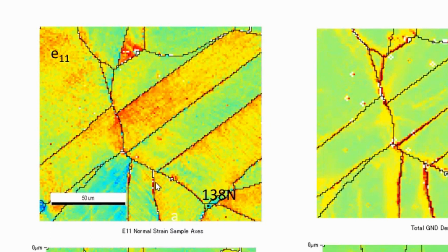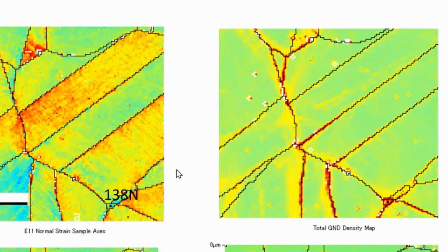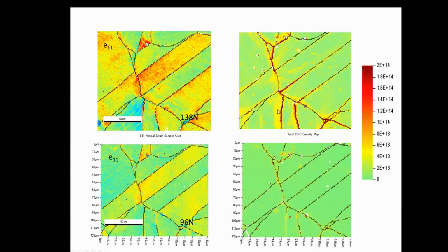And we see little areas where the strain is localized, very, very localized. These are the straight lines I mentioned before, the slip lines. In here, we're looking at the defect structure, where the dislocations are. You see a high buildup of dislocations over here on this boundary. But it's not where the slip lines are on this side of the boundary. You see the strain is very little there, but it's large on this side. So that's a curiosity. That should make people think, why should that be?